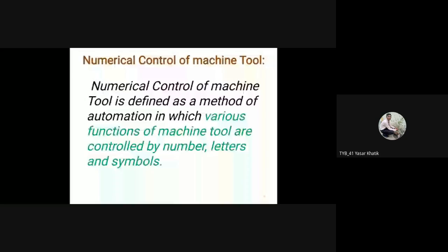Okay, so good. For conventional manufacturing, meaning the lathe machine, the previous machines, there is no tool storage as well as no nomenclature for the tools. But in the CNC and VNC machine there is a tool turret and tool indexing. In our workshop CNC machine, in that tool turret you can store a number of tools, and for the tools you can give numbers like T01, T02, T03.